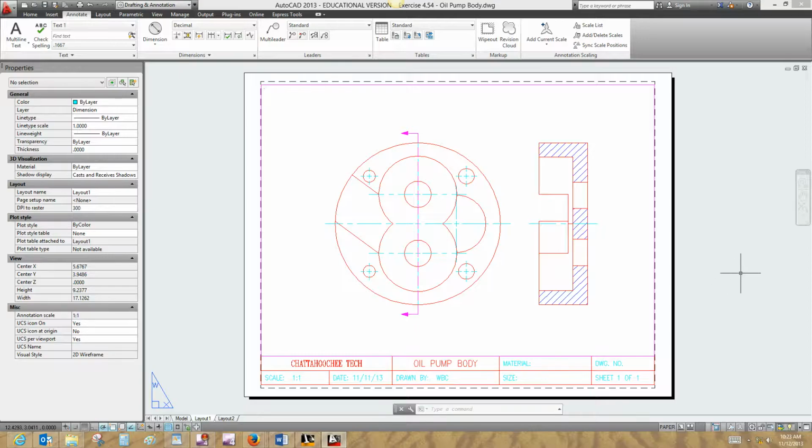Okay, so you don't have to worry about the 4.00 dimension here that's shown in your book. That's just to space the views on the page. Nor do you have to worry about the 3.90 dimension shown here. Please do space your views according to the 3.12 dimension, but we're not actually going to apply that on our drawing or detail sheet. Okay, we're only going to apply the dimensions that are pertinent to the production of the part.